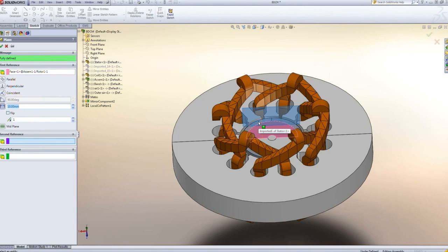Okay, as I said, the same manipulations could be done with all the other quantities as well. Also, now let's say I've had my original design, and now I want to optimize a little bit. So let's say in this permanent magnet here, I used neodymium. These magnets, I used neodymium 42. Let's say I want to use neodymium 52, for instance.